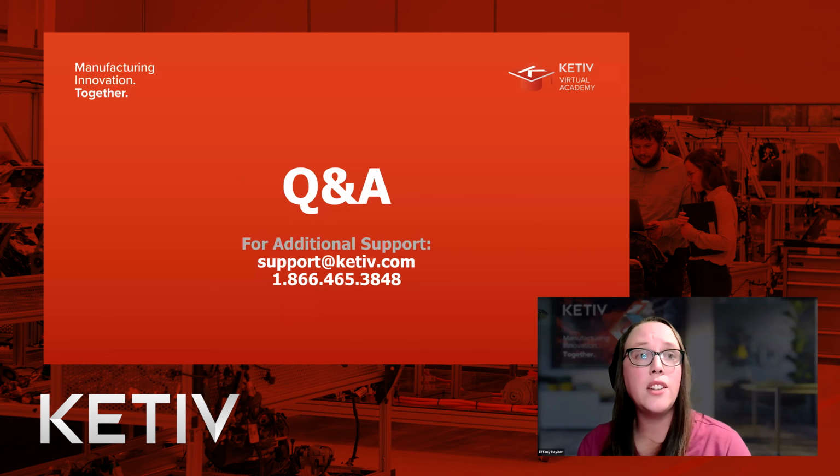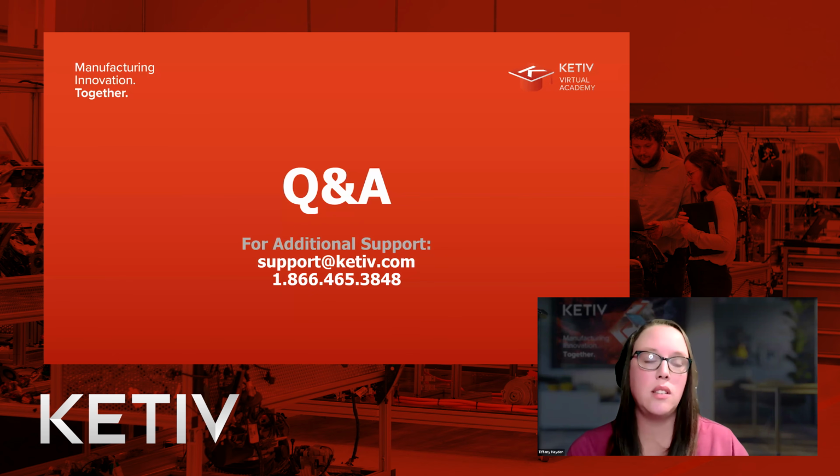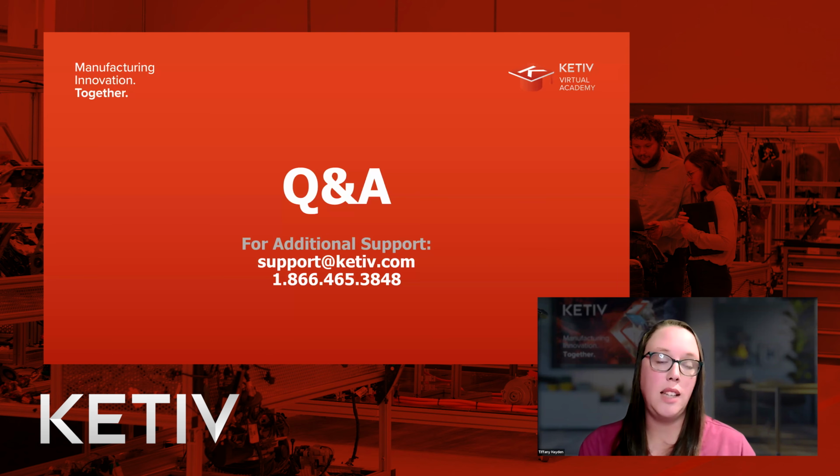Oh, no, unit list will give whole numbers. That's why we had to change it from inches to unit lists. Those are all integers. So that's why you wouldn't want to push a decimal into the quantity for a pattern or anything that you're dealing with quantity. You want to deal with integers, and that's how you do the unit.